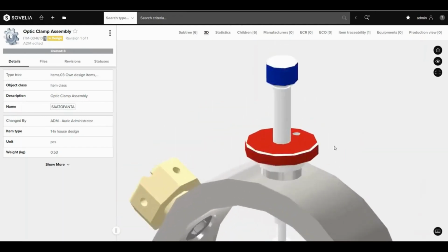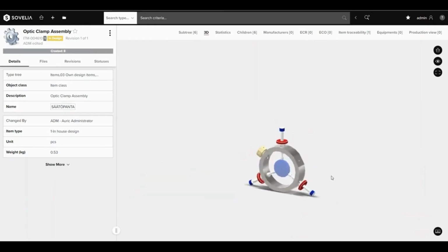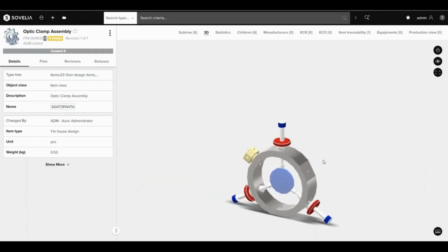Okay, so there we go. There are the main features and functions. A little bonus tip for you here is that if you were to select a particular part or item in the window, you can use your right mouse click now, and you can open the property card. You can pivot and make that the pivot point for your rotation.